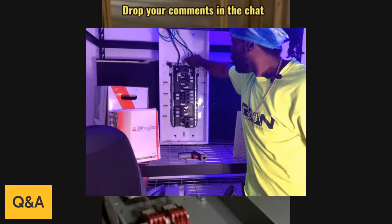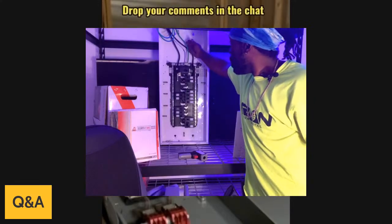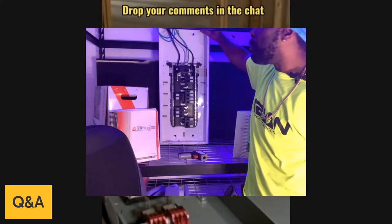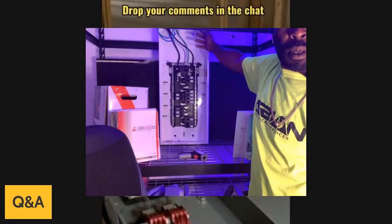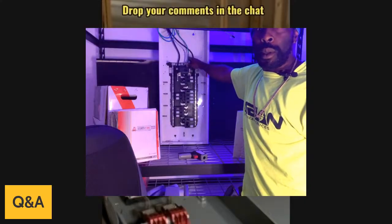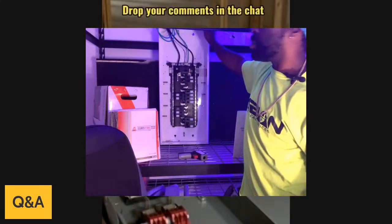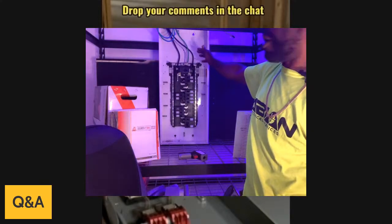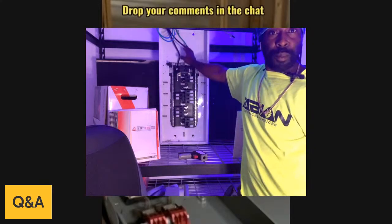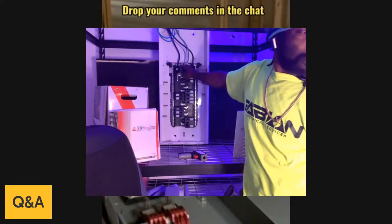You've got the ring screw right here. You also have this right here, which is your lugs. You also have your ground wire coming in. What this ground wire does is it goes over to the actual underground service, which is going to go onto a ground plate. This is my service conductors coming in here.